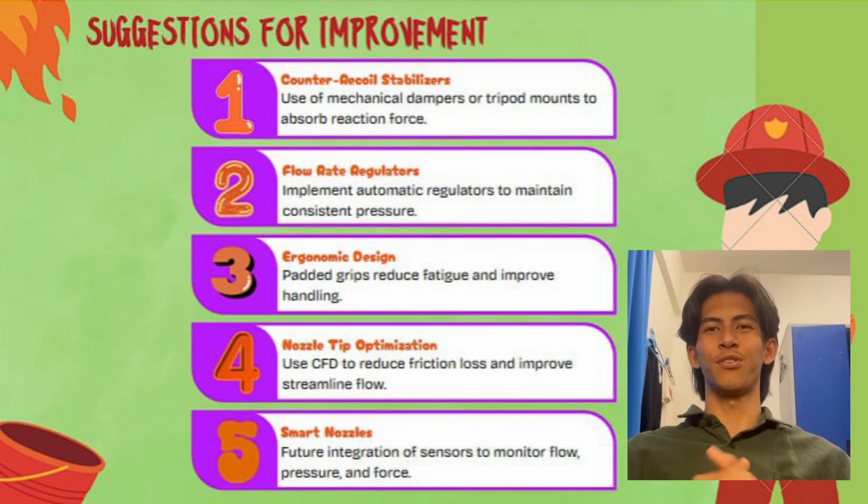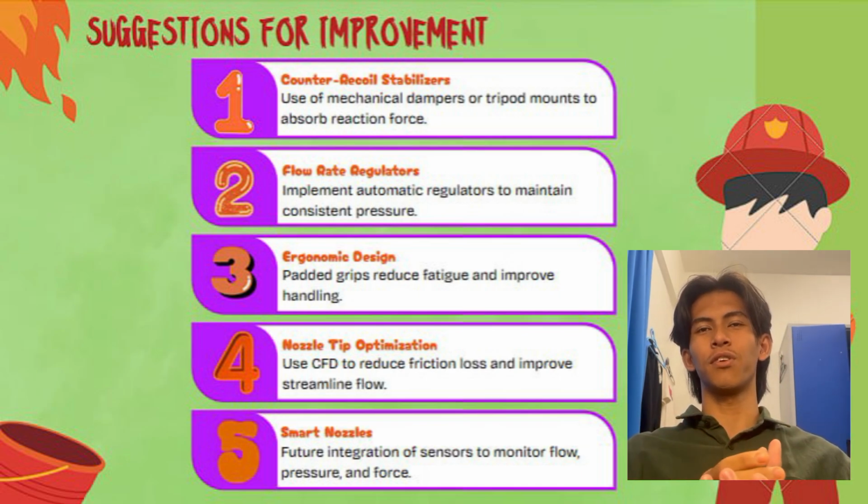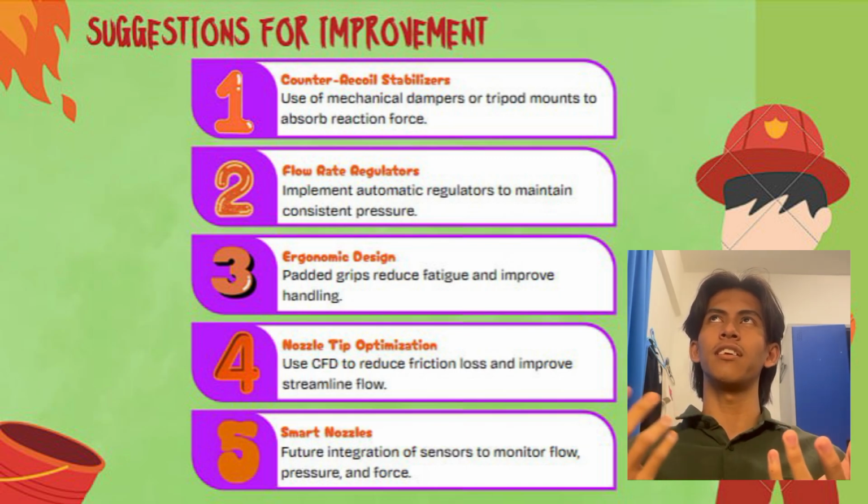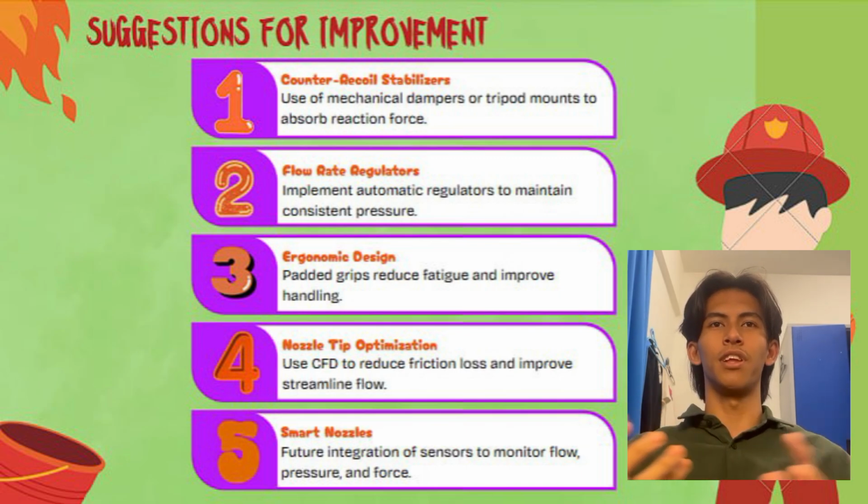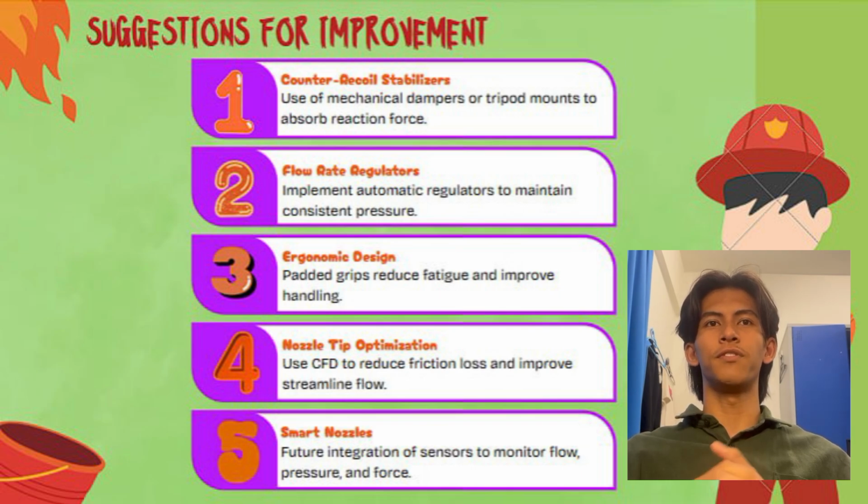Third, design the nozzle with an ergonomic pad grip to reduce wrist fatigue and improve maneuverability. So when we grip the hose, we can easily control it. And finally, consider a smart nozzle. Equip the system with sensors to monitor pressure, temperature and flow rate in real time. This can aid both training and live operations.